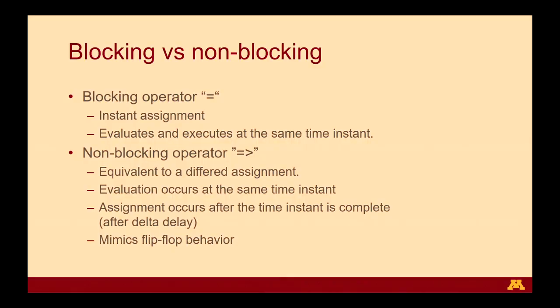So in the case of a flip-flop, if you imagine that a positive edge comes, it will evaluate all the inputs at the positive edge, but it will drive the output only after the positive edge has completed, in a way to mimic the behavior of how a flip-flop behaves, right? So I hope that the difference between a blocking operator and a non-blocking operator is clear.